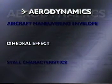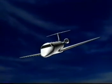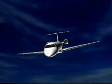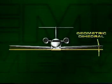The dihedral effect. Every pilot knows that yawing an aircraft also causes it to roll. This is valid for either type of aircraft. It doesn't matter if it is a turboprop or a jet, a straight wing or a swept wing. This is called the dihedral effect. You know, dihedral is the angle of the wing with respect to the horizontal line, as seen in the picture, which causes an interesting aerodynamic effect.